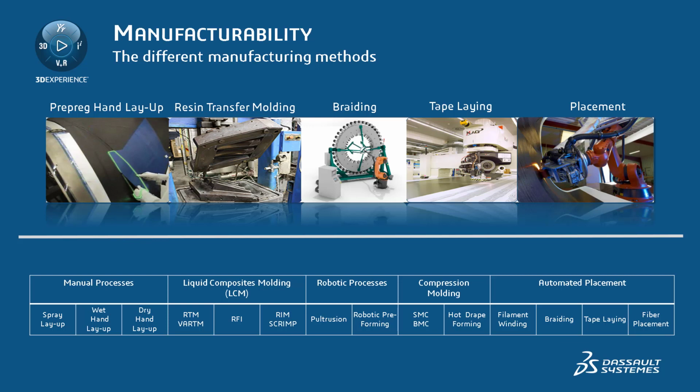The different fabrication techniques can either be classified as direct processes like RTM, pultrusion, or contact molding that use separate fibers and resin brought together at the point of molding, or indirect processes that use fibers pre-impregnated with resin like vacuum bag/autoclave molding or compression molding. Generally, hand layup of fabrics or UD tapes are currently the most common manufacturing techniques.